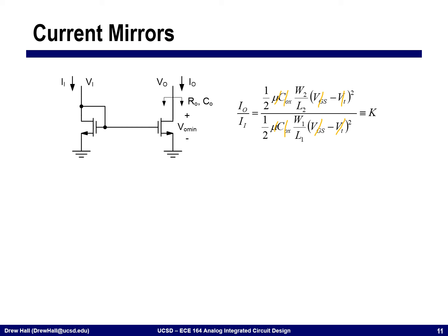We talked a little bit about this, but just to remind you, oftentimes we want to leave the length of the device fixed. While it looks like it's a free variable to change here, in practice it changes a lot of the second order effects of this device. And so you'll often leave these two devices to have the same length and simply change the width in order to mirror the currents around for this ratio.